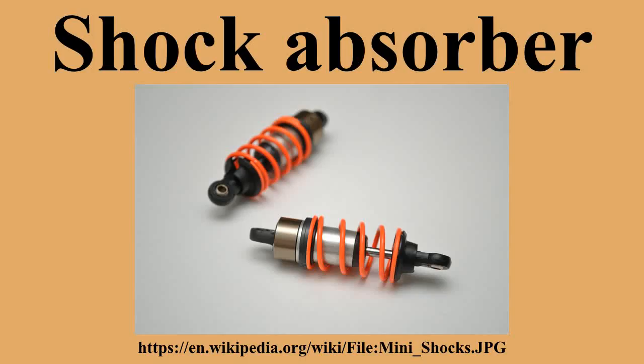The Telesco unit was fitted at the rear end of the leaf spring in place of the rear spring to chassis mount, so that it formed part of the springing system, albeit a hydraulically damped part. This layout was presumably selected as it was easy to apply to existing vehicles, but it meant the hydraulic damping was not applied to the action of the main leaf spring, but only to the action of the auxiliary spring in the unit itself.